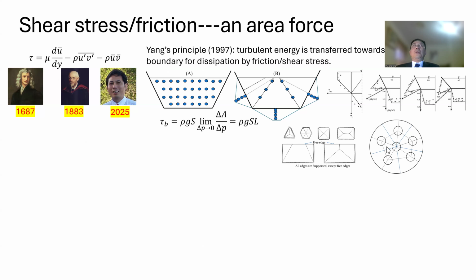If you want to know which pile affects the soil in this region, you can also draw the normal lines, and you can say this region will be affected by this pile, and this region will be affected by that pile. This is an assumption. I don't have the experimental data.